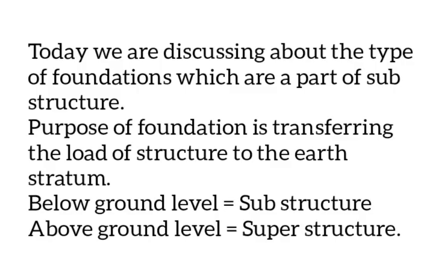Today, we are taking a view on the types of foundations. The purpose of foundation is to transfer the structural load to the earth stratum. In construction, structure below ground level is called substructure, and the structure above ground level is superstructure.